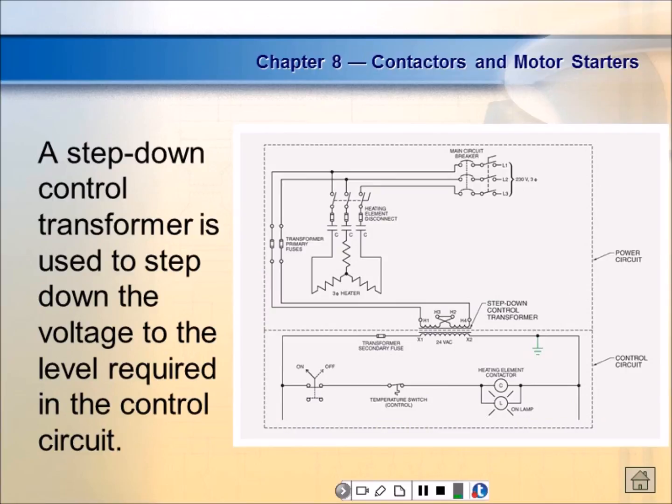This is the low voltage transformer. It's wired for high voltage or low voltage. Yeah, it's wired for high voltage. We hook them in parallel for low voltage and series for high voltage.